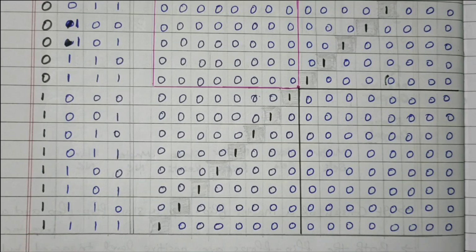In this video we discussed how to construct the 4 into 16 decoder, a 4-input, 16-output decoder, using two 3 into 8 decoders. Out of 4 inputs, we use 3 inputs for both decoders. One more input is used to enable or disable decoders 1 and 2. So we get 8 different outputs when D equals 0, and another 8 different outputs when D equals 1. So in total we get 16 outputs.